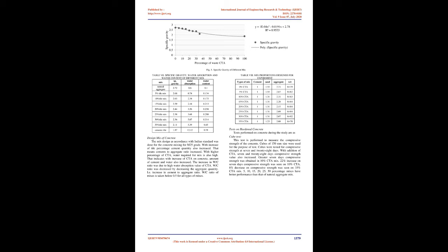Coarse aggregate. Coarse aggregates used for the study were natural aggregates and grinded ceramic tile aggregate. The sample of ceramic tiles are collected from Bijan suppliers, Shahid Chowk, Pokhara, then it was grinded by manual hammering and sieved as per IS Sieve. Few tests: specific gravity, water absorption, water content, impact value, on tile samples were done on Pashchimanchal Campus Lab. Natural aggregates were crusher run aggregate obtained from crusher located in Pokhara.